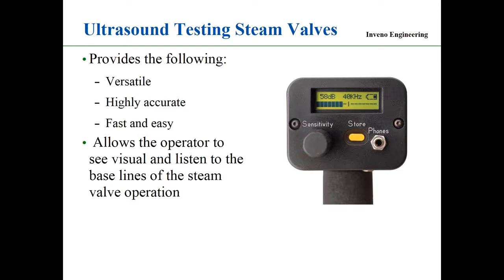The high frequency ultrasound unit gives me a display of the ultrasound that I'm picking up, which is a visual, and it also gives the operator of the unit the ability to hear that sound. The high frequency ultrasound is heterodyned into an audible sound, so you can listen with a headset. So you get a visual, and you also get to hear the valve if it's leaking through.